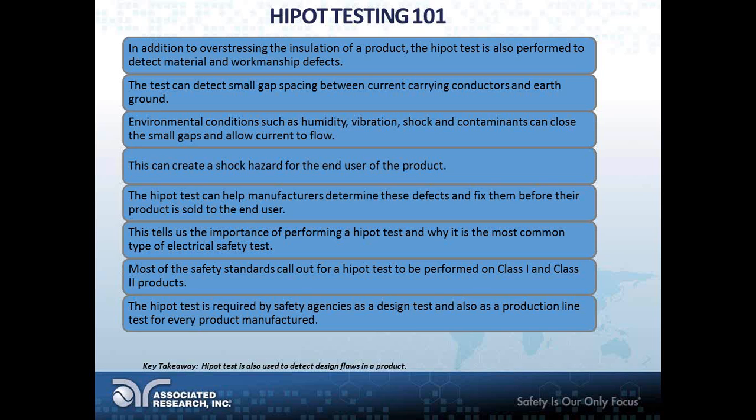So the Hipot test falls under the design test and production line test, which again stresses how important this test is. So the important point to note here is that the Hipot test can also be used to detect design flaws in a product in addition to stressing the insulation of a product.